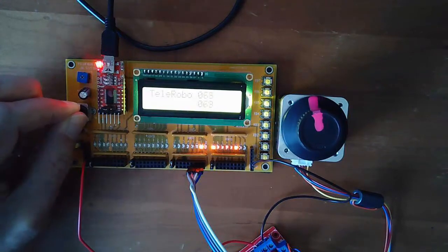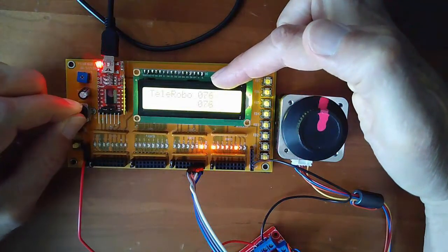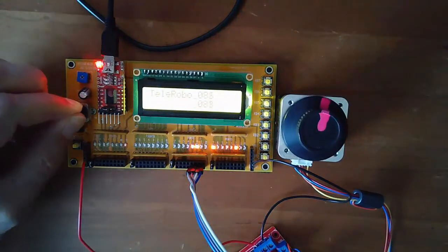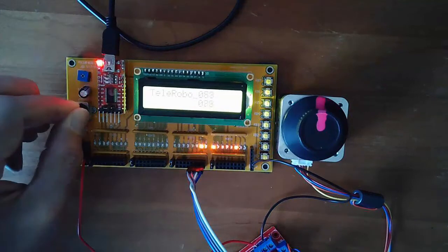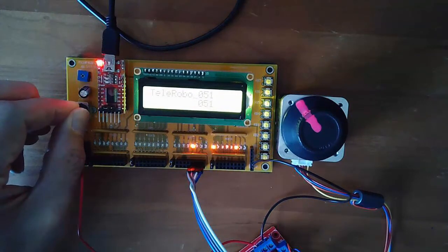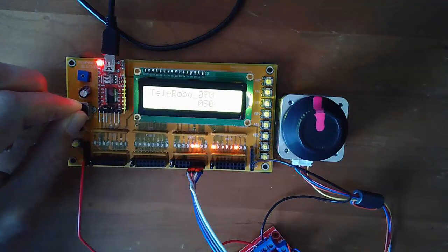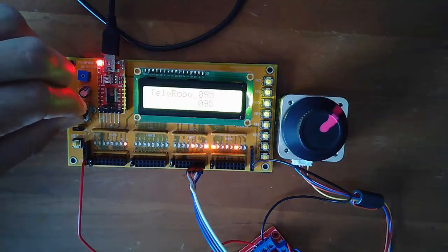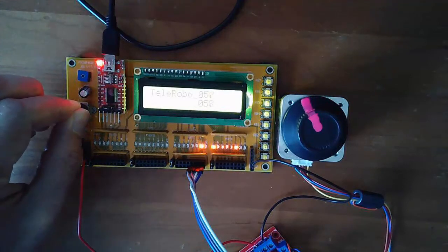And what you see on the LCD display, the top number is the desired angle, that's the reference, where it should be. The bottom number is the actual number of steps. And what it does, if I change quickly, that's the slew rate. Every pass it goes through the loop, it says if I am too low, go forward one step. If I'm too far, go backwards one step. So this is going forward one step, going backwards one step each time it goes through the loop. If I stop moving, it also stops.